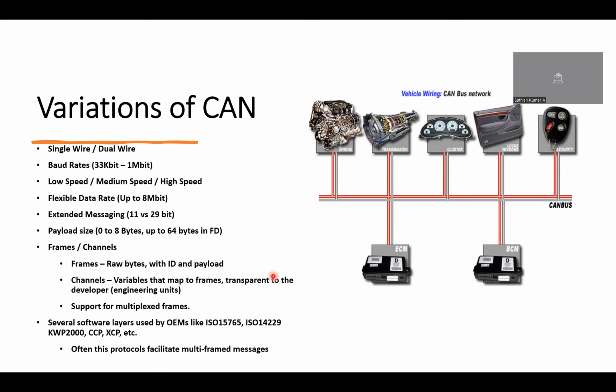For example, the frame has 6 or 7 channels. Channels are basically signals. It has 6 or 7 channels related to temperature. For example, we can call engine temperature, pedal temperature, outer temperature, cluster temperature, environment outside temperature, and chassis temperature, like that. So we have multiple temperatures. All the temperatures will come under the single frame, so it will be with multiple channels.